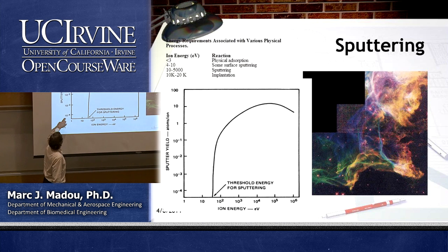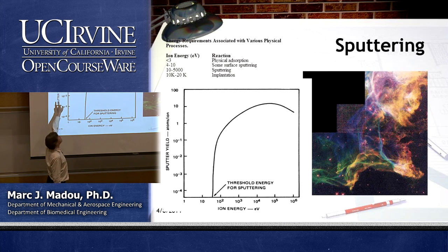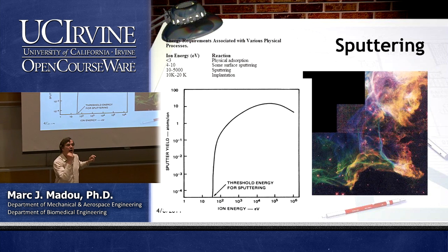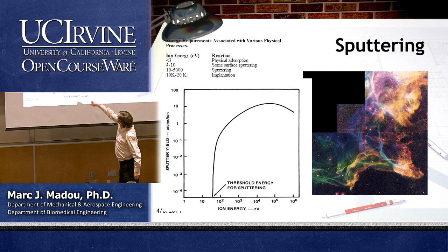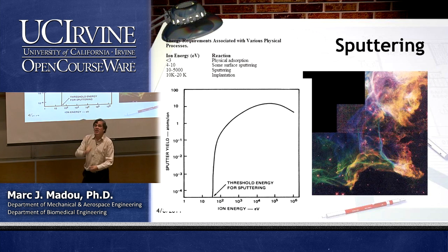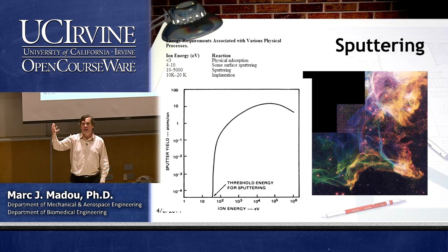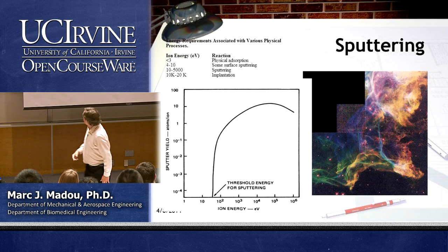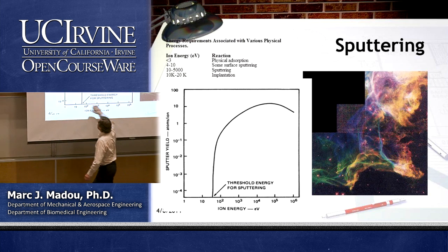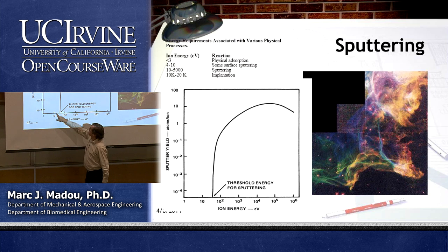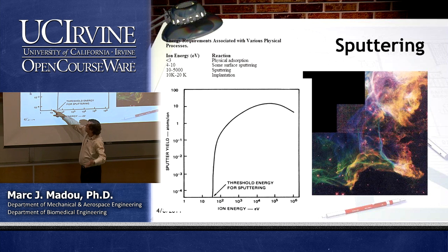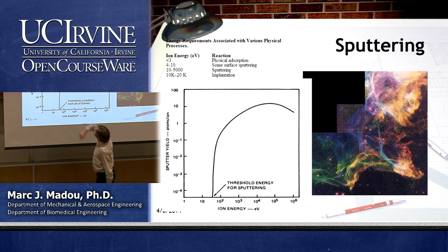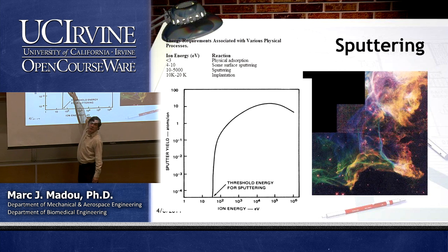This curve here, since I still have a bit more time, in a way follows up on these 4 items. Here it shows sputter yield. That means number of atoms I kick off per ion that comes in. So yield, for example, if I have 1, that means each ion that comes in kicks off 1 atom from your workpiece. And this axis is the ion energy. So you guys already know, if it's less than 10, I'm not kicking off any atoms, yeah? I might be sputter clean.